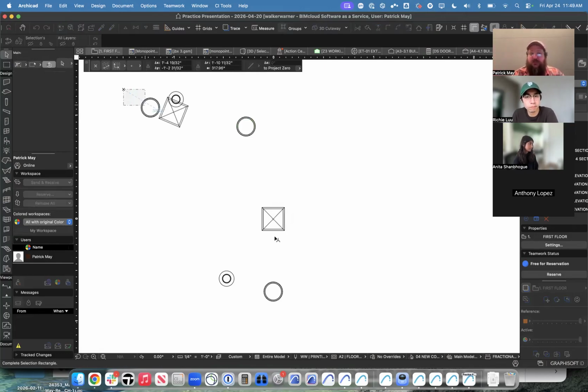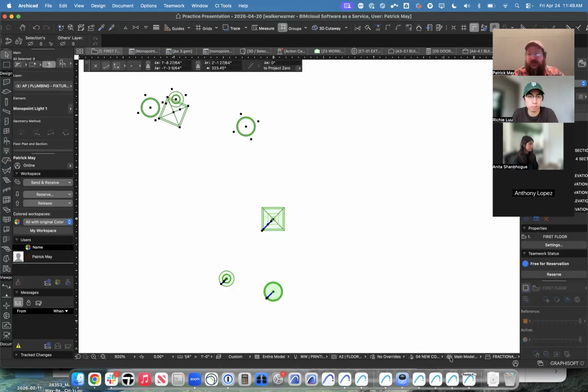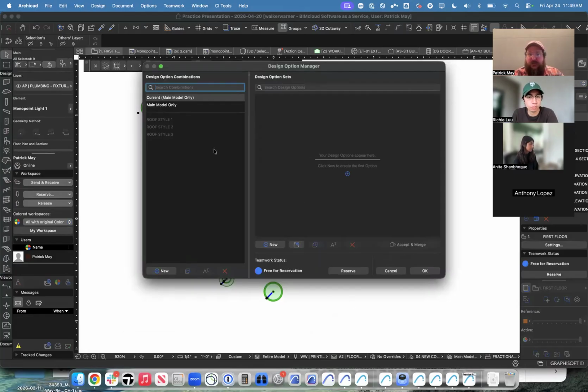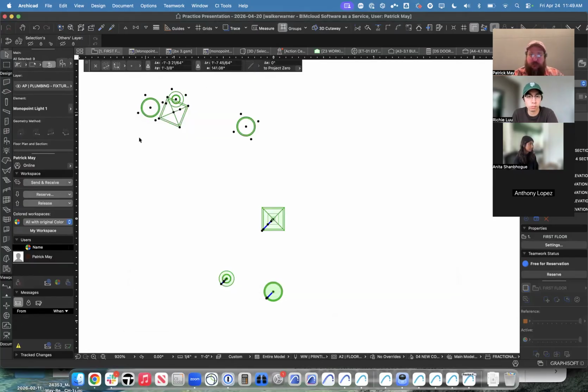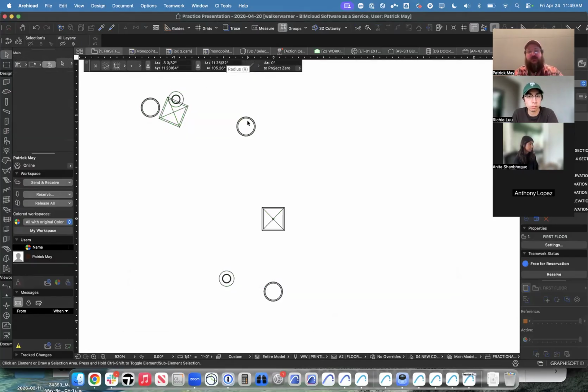One thing that I actually picked up recently that I hadn't thought of, and I'm going to build this into the template pretty soon, is using a design option for these basic primitive elements, like the shells and the morphs and the meshes and beams and columns that you model these fixtures with and save as an object later.